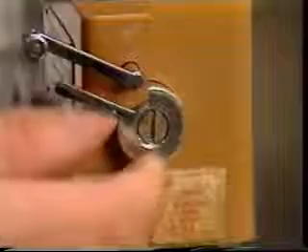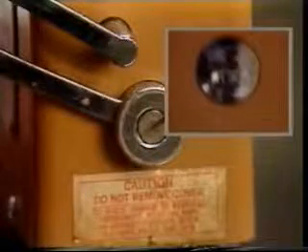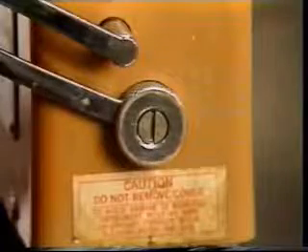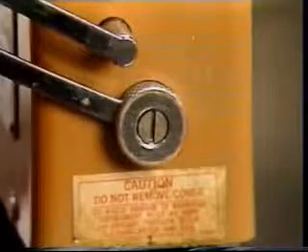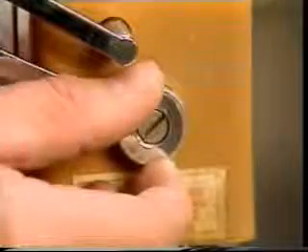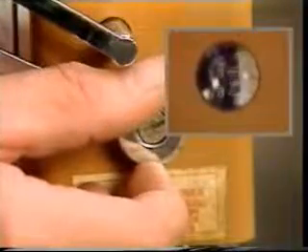With the speed lever still at the 300 RPM setting, the gel strength knob is slowly turned clockwise while the indicator dial is observed. The dial will peak and then break back. The peak reading is recorded as the 10-second gel strength. After letting the mud rest for an additional 10 minutes, the gel strength knob is again turned clockwise while the indicator dial is observed. This peak reading is the 10-minute gel strength.